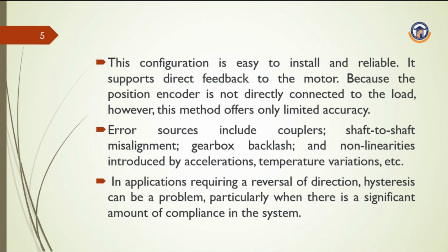This configuration of position encoder is very easy to install, it is more reliable, and it also supports direct feedback to the motor. The position encoder is not directly connected to the load. However, this method provides only limited accuracy. We cannot suggest this method for many applications.